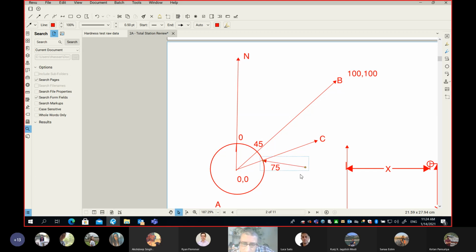What does it represent? Your azimuth, because it's referenced to north. Exactly. Only now, and not before the backside. After you do the backside, the reading has a meaning, because the 0 is not randomly oriented on site. However, the 0 is pointing to the north of the site. And that's why the 75 is the azimuth.